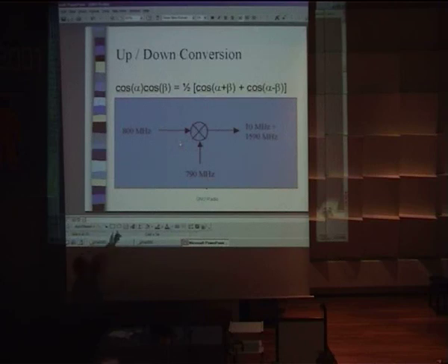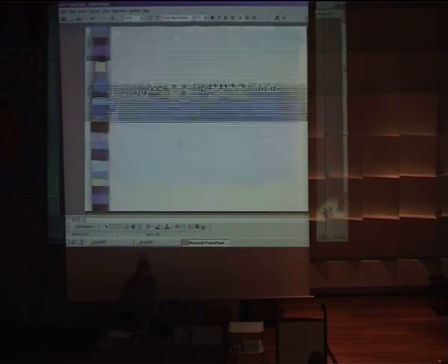And there's a bunch of tricks. For example, we can talk later, I'm going to present a regular superheterodyne radio and then a software version and how they go. But there are a bunch of different engineering trade-offs you can make, because this can be a complex multiplier in software, but it's hard to do a complex multiplier in analog hardware. So you get both of them out, and then there are all kinds of tricks that occur.